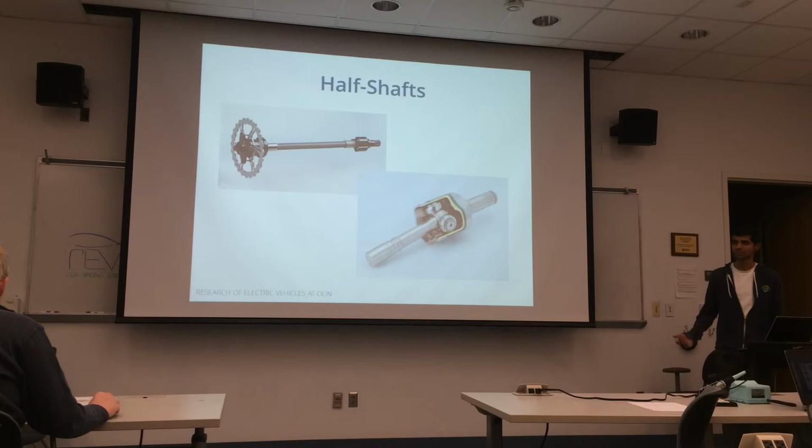And this is where we use a CV joint, which is a constant velocity joint. The ones we use are tripod housings, which you can see over here, which basically allows the entire shaft to bend up and down, but still transmit power. These get less efficient as they bend up and down even more, but for the most part, they're really good at transmitting power across a variety of bump conditions. And then the half shafts, we're running carbon fiber half shafts, which just connect the gearbox in the middle of the car to the rear wheels.